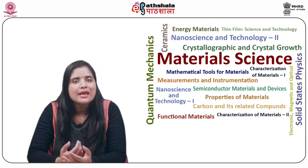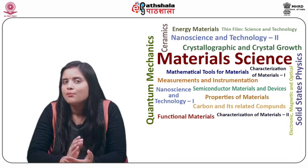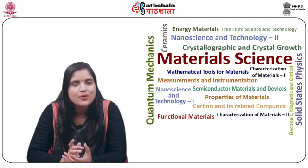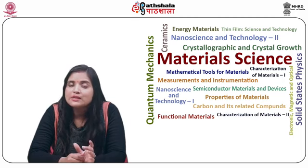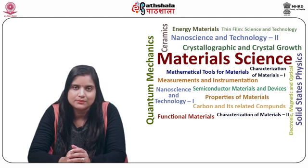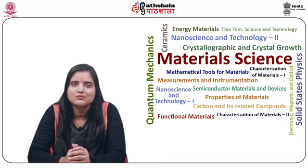Ball milling is extensively employed to grind materials like coal, pigments, and feldspar for pottery. Both wet and dry grinding are possible. However, wet grinding is usually done at low speeds. Ball milling increases the solid-state chemical reactivity in multiple component systems. Furthermore, it can also be used to produce amorphous materials.